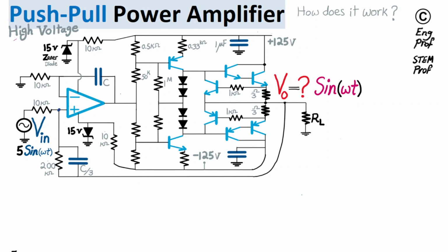A high voltage push-pull power amplifier circuit is shown in this example and analyzed in this video. This circuit is implemented with one low power, low current op-amp as shown here, and then at the output stage we have a Darlington transistor pair in the form of a BJT NPN transistor pair, and a bipolar junction transistor PNP pair, and then we have current limiting transistors, and just a current source effectively in the circuit that provides the initial current for further amplification.